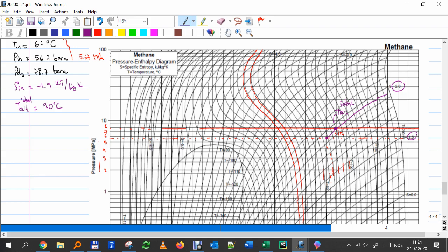The isentropy lines are these lines shown here. You see S0, this will be -1, so this will be -2, -0.2, -0.4, -0.6, -0.8, -1. So I move on that line all the way here until I end up on that pressure. That's ideal. The best I can do to compress this gas from here to here is by following that line.